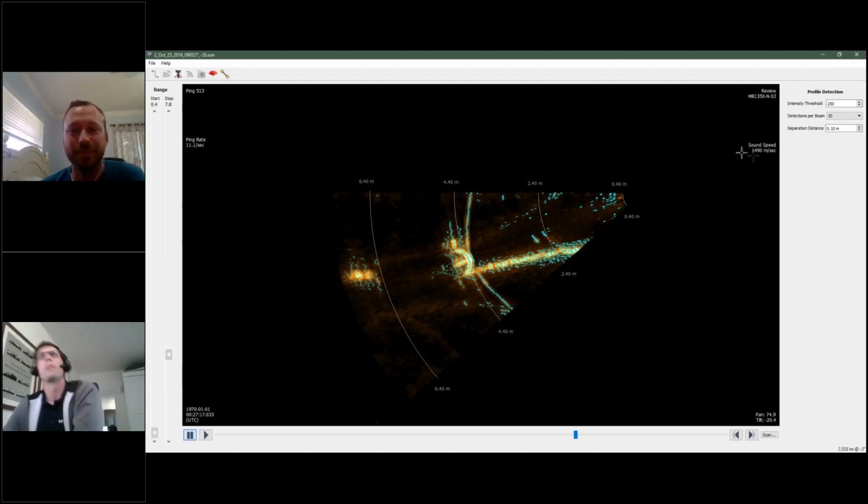Yeah, so good to keep in mind as a tool in your toolbox, but I would usually just stay at a few detections per beam. This is really just if you're looking at your point cloud and you're saying, oh, I have that object in the foreground that I also wanted to pick up in addition to the object in the background, maybe your structure. If you want to pick both, you can try setting that to 2 and rerunning it to get more points. Generally, you're going to have more cleaning of points the higher the detections per beam. And separation distance is tied to that.